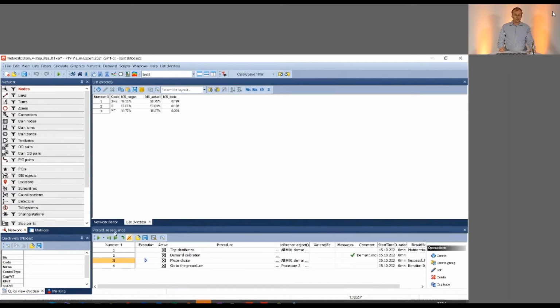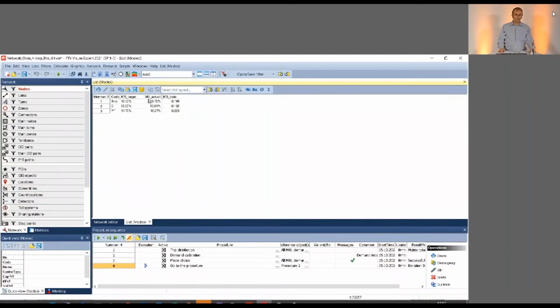Okay, and I run it. Okay, mode choice model has run. The actual values here do not automatically adapt. It is not a formula attribute or whatever. It is updated when I run the demand calibration add-in again. And now, hopefully you see that the actual values are nearer to the target values than they have been before. And again, I have a new, better estimation of beta.